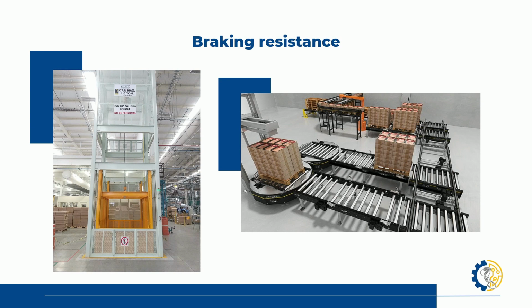And it's also going to break through inertia and not by ramp. So if we wish to respect our deceleration ramp, and we wish to have a more exact brake, then that's where our brake resistance comes in. So we generate an excessive force of brake. And therefore, our drive is basically going to be blocked. It's going to stop our motor all the way until it's physically allowed to do so. So that's why we need to be very careful if we need the brake resistance or not.